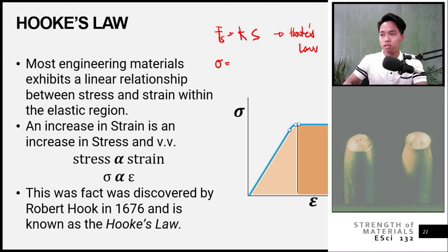And also your deformation, your S here, is your final length minus your original length. That is simply equivalent to our delta, the final minus the original. So your S here can be related as a function of strain. We can make it strain. Therefore, we can relate your stress and strain using, again, the concept of Hooke's law.